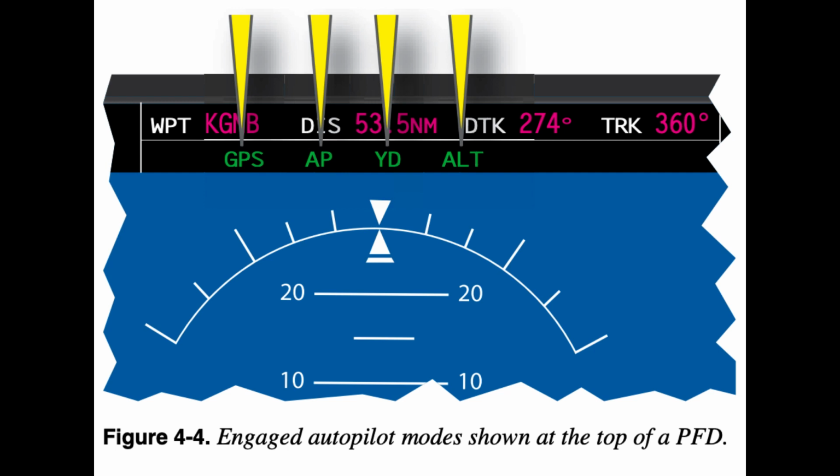Before any control movements are made, the Autopilot/FD must first determine which control movements are necessary, e.g., left or right turn. To do so, the FD/Autopilot must first determine the aircraft's current heading and bank angle, determine amount and direction of the turn, and then choose an appropriate bank angle, usually up to 30 degrees or less. To make these determinations, the FD gathers and processes information from the aircraft's ADC, airspeed and altitude, magnetic heading reference instrument, and navigation systems.